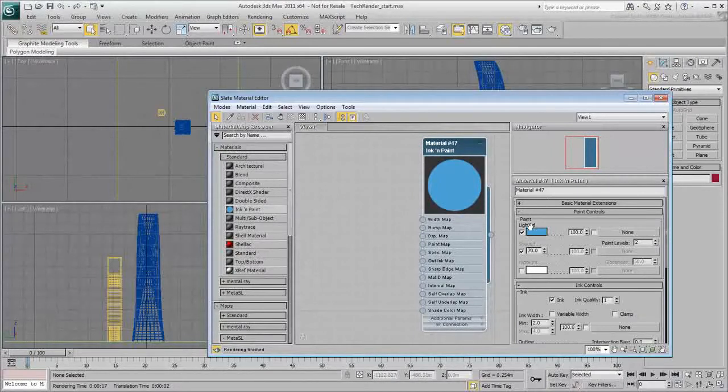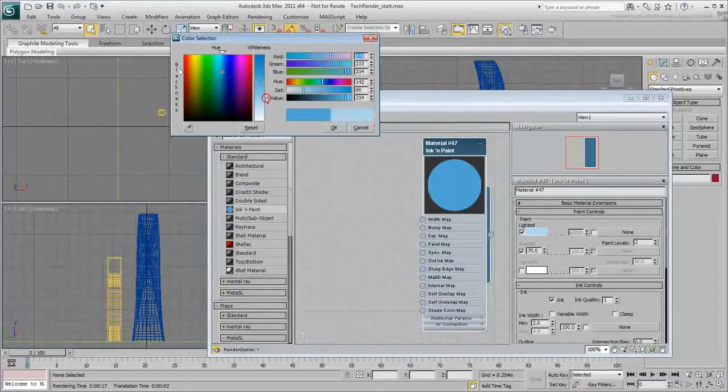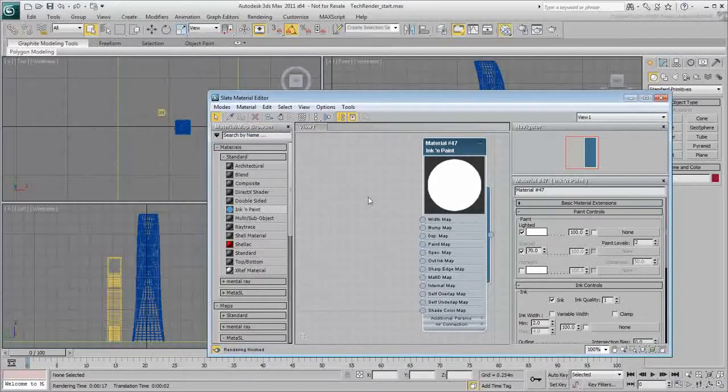Ultimately, you're looking for a monochrome image, so start by setting the lighted color to full white. You can also change the paint levels to affect the shaded areas. For the effect you are aiming for with the scene, a value of 3 should be adequate, but feel free to experiment with other values. The % option lets you adjust the intensity of the shade.